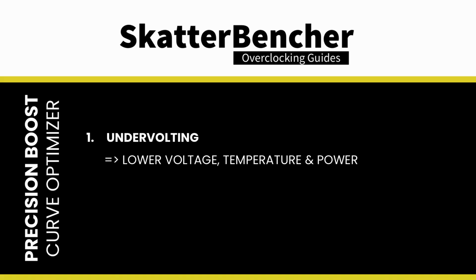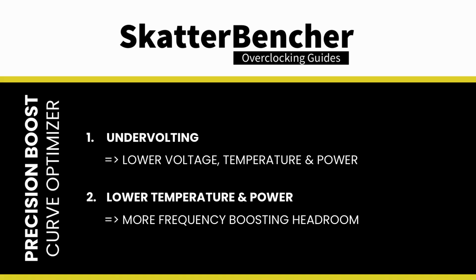Most commonly, we would set a negative curve optimizer, and it helps in two ways. First, undervolting lowers the operating voltage, temperature, and power consumption. Second, as a consequence, the Precision Boost 2 algorithm can leverage the additional headroom to boost to higher frequencies. So you tend to get lower temperatures and higher performance. It's a win-win. However, there are a couple of caveats when it comes to using Curve Optimizer.